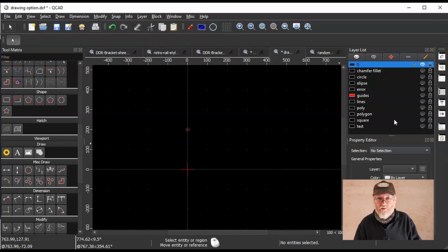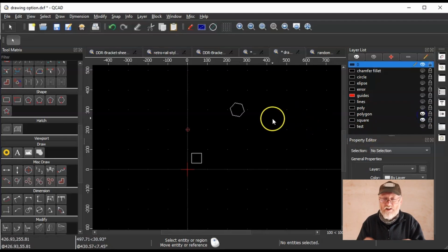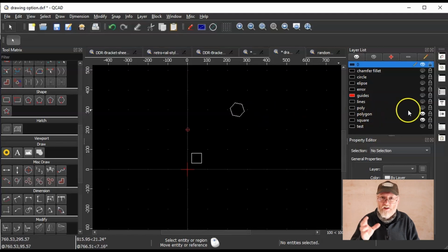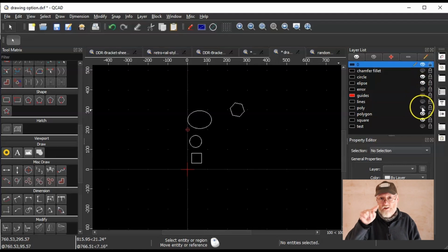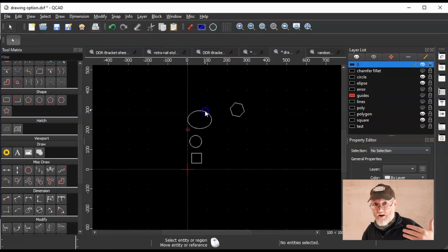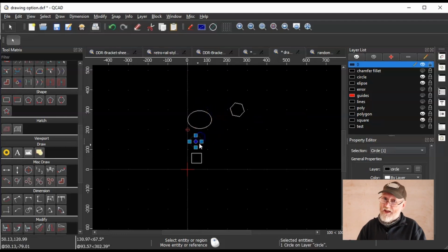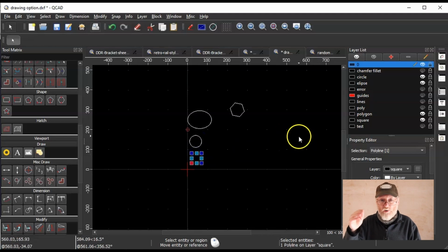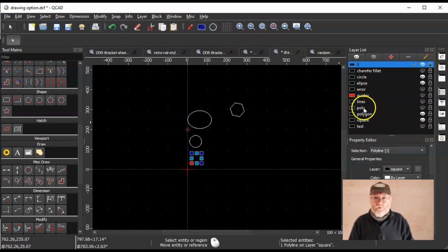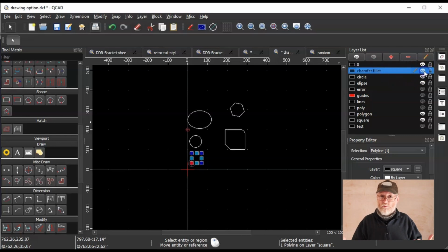Suffice to say that one of the main issues I find is, for example, when you get a polyline drawing of a part that is fairly geometric, that requires screws, for example, placed in certain positions, and they have a certain dimension. Invariably with a polyline, it's just a random squiggle that's a vaguely circular shape, and it has no center marking. Now clearly you need a center mark to both define its diameter or radius, but also for its location within the part, wherever it's going to be. So unless you're doing lots of squiggly lines sort of stuff, most of the time you're going to be making parts that require fixed shapes.